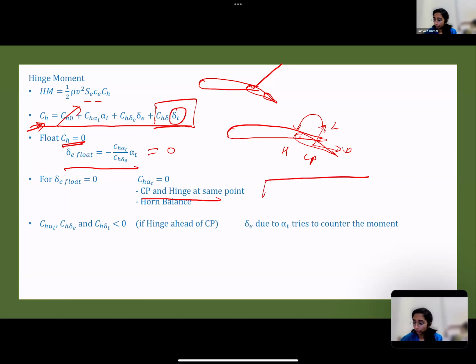So this is your entire vertical horizontal tail. And this is the deflectable portion. This is your elevator. So usually it's only towards the end. Now you keep some area here which can be deflected too. So if this is your hinge point, all the forces acting in this area, in this and this, will produce a restoring moment.